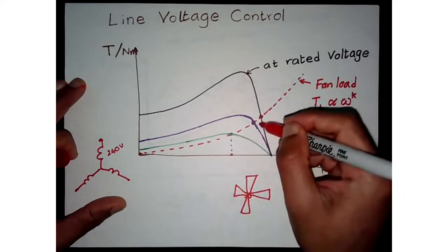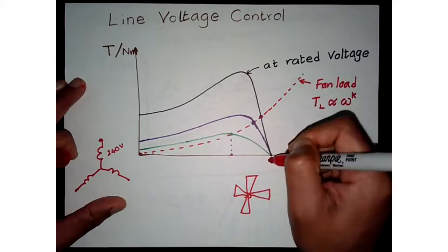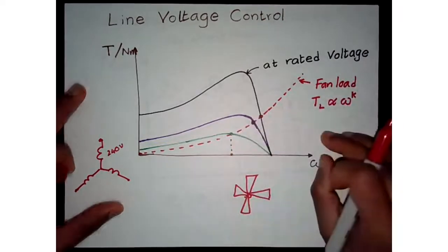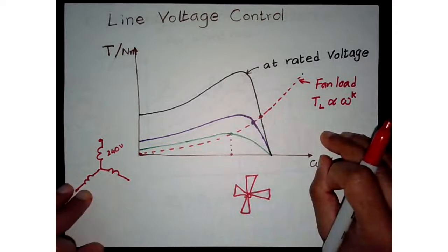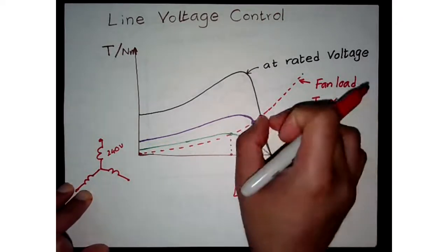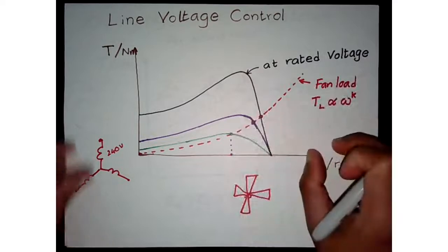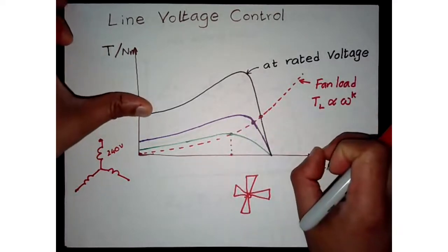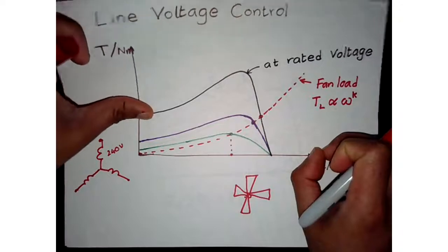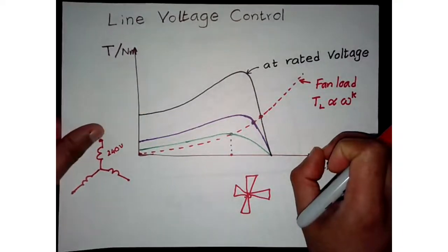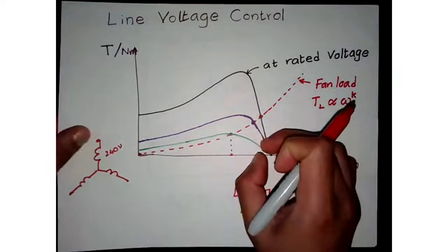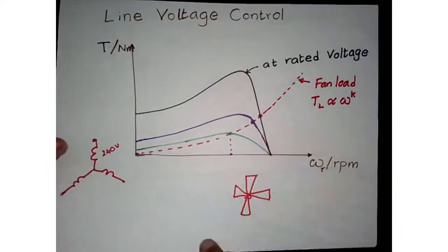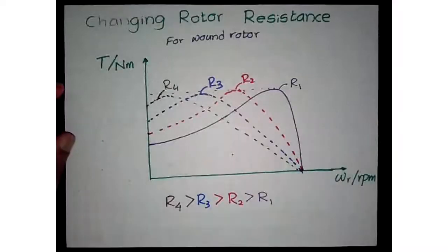As you get closer to the synchronous speed, you have much finer control, because your resolution decreases; the curves are very tight close to this point. So by controlling line voltage, you can control the speed, but it applies to certain applications, not a whole lot of them.